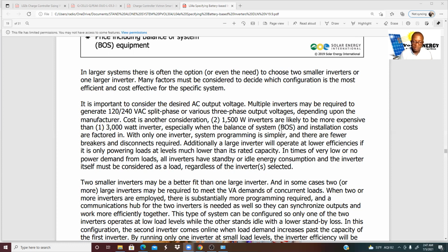So in the instance wherein one inverter fails, I can still use one inverter to run the smaller power in that home until we can replace the inverter that had a problem. So it's better than having one big inverter, where in a scenario with a problem, they have no inverter to invert the DC load to AC load for that system.